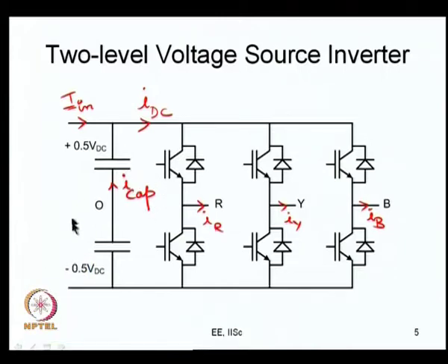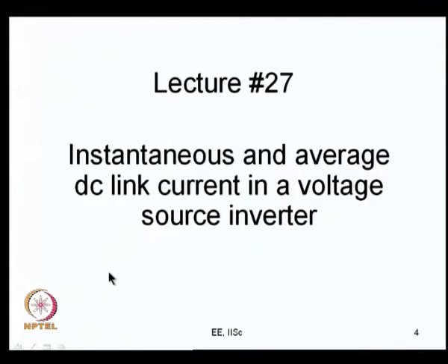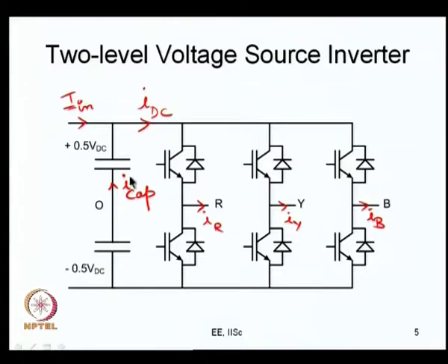In sizing the capacitor, there are two things. One is you have to make sure that you have big enough capacitors such that the voltage ripple is very small. That depends on what is there on the DC side, whether you have a rectifier and all those issues also. But in general the philosophy is the value of C should be chosen such that the voltage ripple here should be very small. And the next important rating of a capacitor is its RMS current. You have to make sure that the capacitors have enough RMS current rating. So, in that sense also it is important.